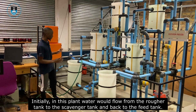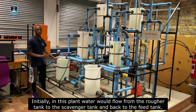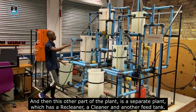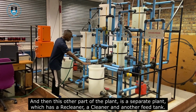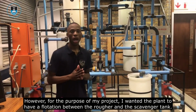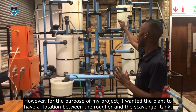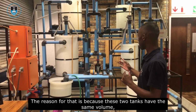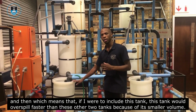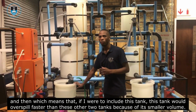Now initially in this plant, water would flow from the rougher tank to the scavenger tank and back to the feed tank. And then this other part of the plant is a separate plant which has a recleaner, a cleaner, and another feed tank. However, for the purpose of my project, I wanted the plant to have a flotation between the rougher and the scavenger tank. And the reason for that is because these 2 tanks have the same volume, which means that if I would include this tank, it would overspill faster than these 2 tanks because of its smaller volume.